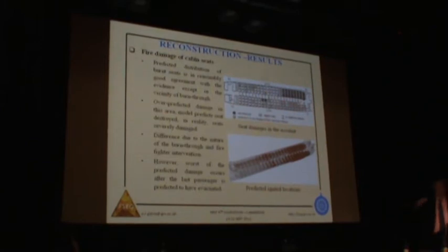I want to just briefly show you how good the fire simulation was. This is at the end of doing the 3 iterations in this loop. We got pretty good agreement. What I'm going to show you here are some of the differences. This diagram shows you the damage to the internal seats. These dark seats here are completely burnt out, and these dark seats in our model are completely burnt out. These hatched seats here are severely damaged but not completely burnt out. And in our model, near where the fire entered, we also have completely burnt out seats. So we are overestimating the damage to the seats at the point of the fire assault. We've overpredicted the damage in this area.